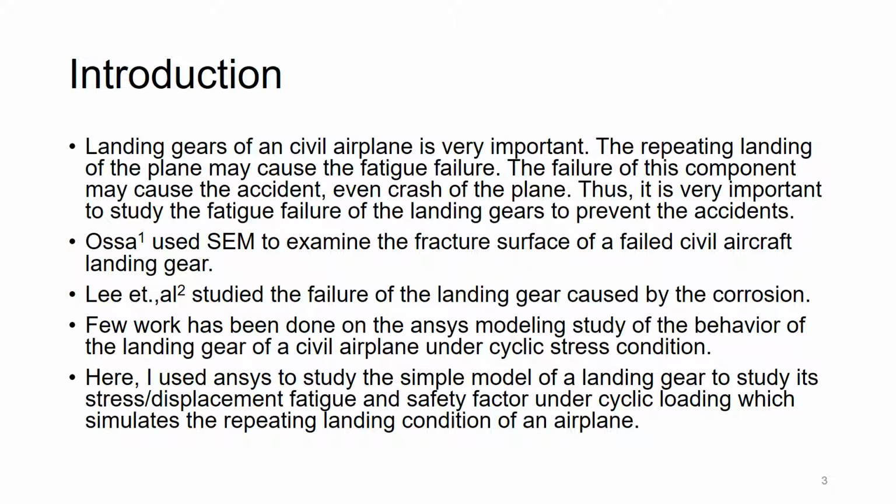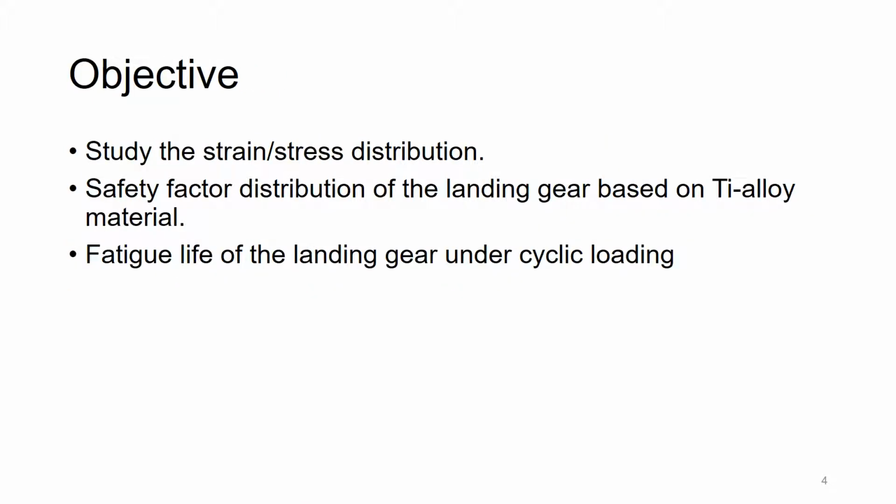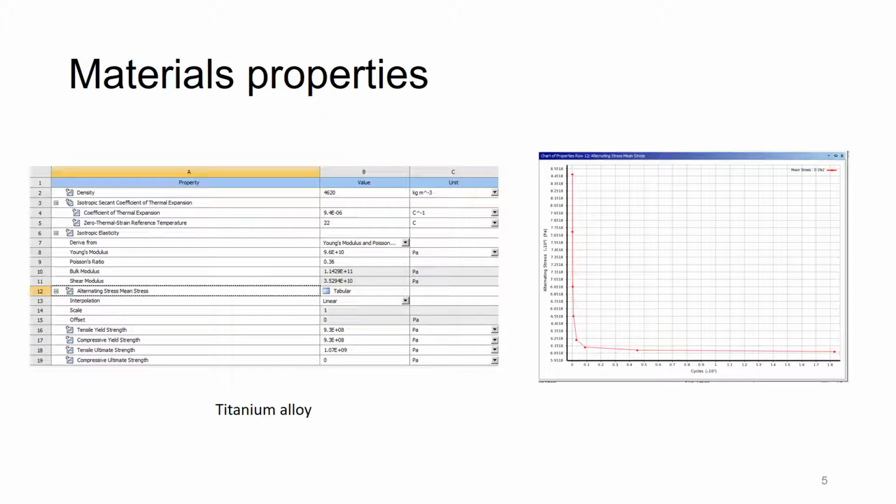So here I use ANSYS to study a very simple model of a landing gear to study stress, displacement, fatigue and the safety factor distribution under cyclic loading. So this will also simulate the repeating landing condition of an airplane. So my objective is to study the strain, stress distribution, safety factor distribution of the landing gear based on the titanium alloy materials, and also the fatigue life of the landing gear under cyclic loading.